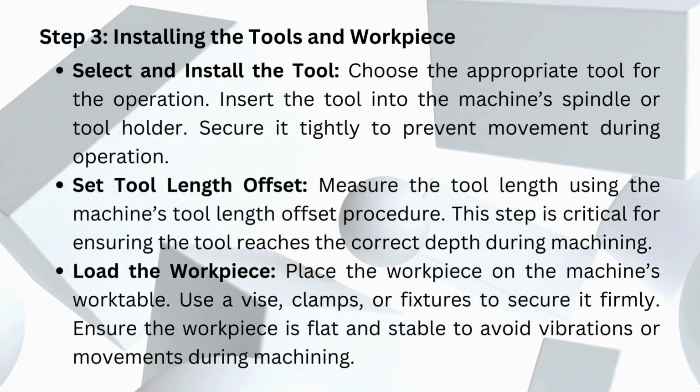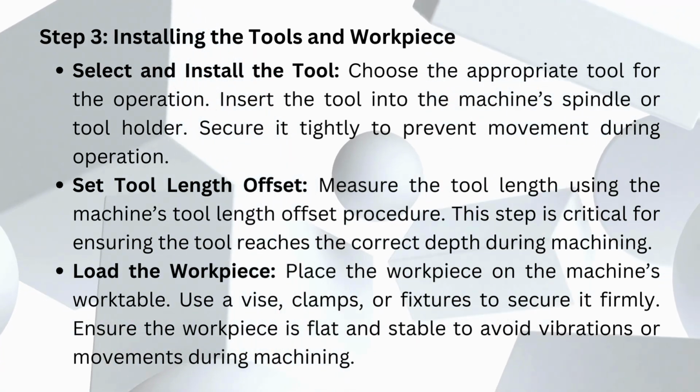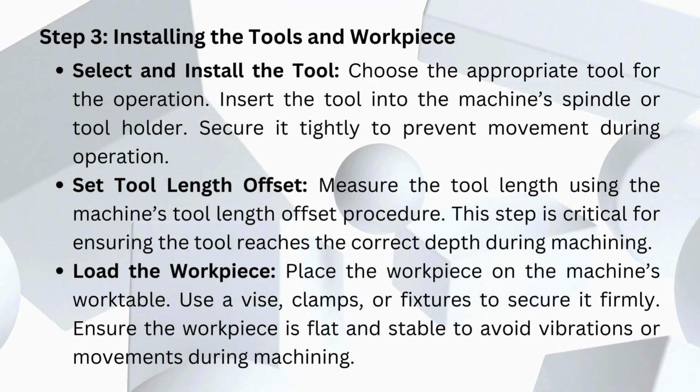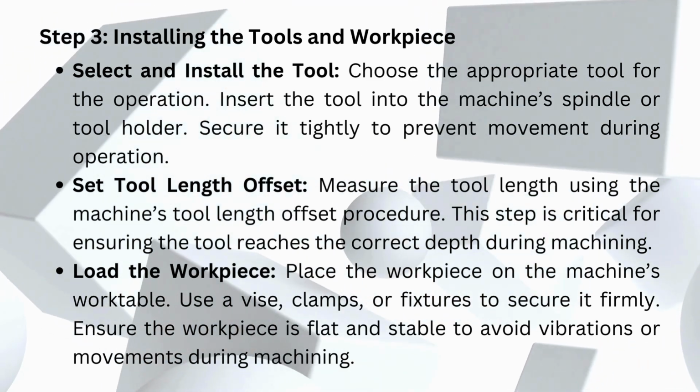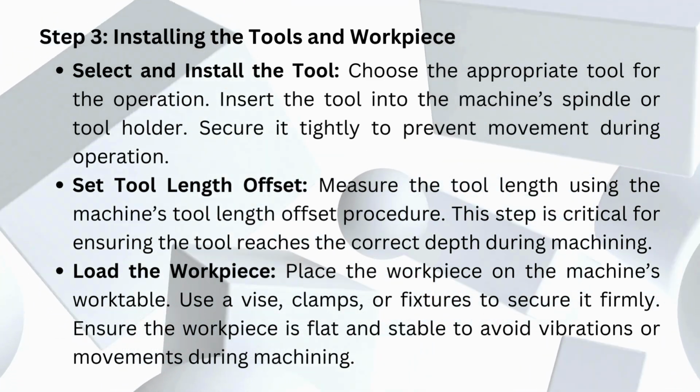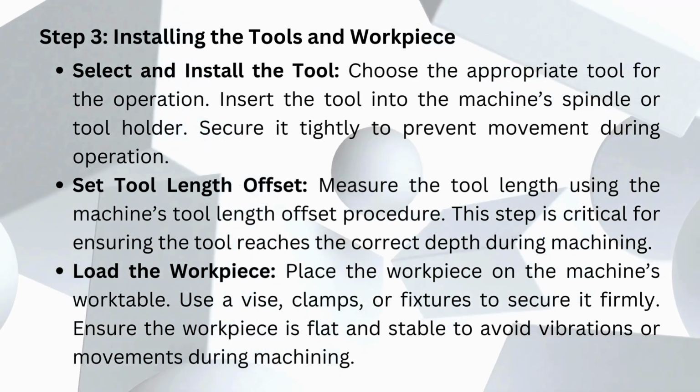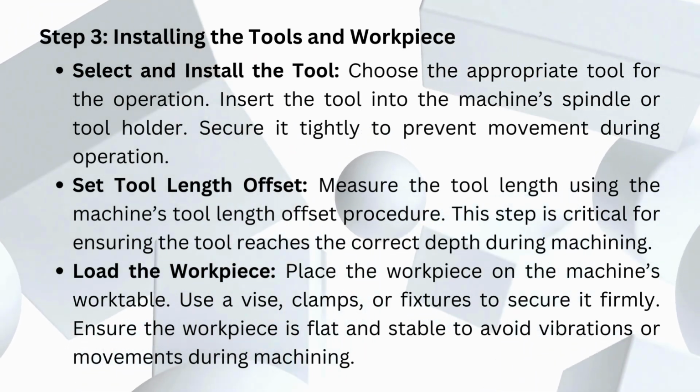Load the workpiece. Place the workpiece on the machine's work table. Use a vise, clamps, or fixtures to secure it firmly. Ensure the workpiece is flat and stable to avoid vibrations or movements during machining.